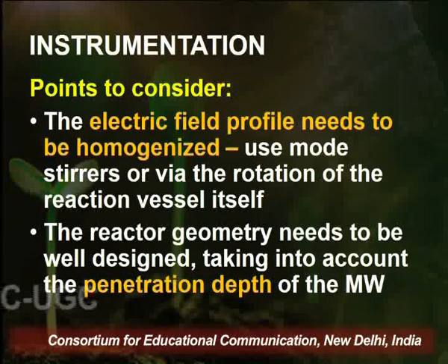We will discuss how this rotation happens further when we discuss the microwave extractors or their components. Then the second point that has to be kept in mind is the penetration depth of microwave. As we discussed, the heating by microwaves is also dependent upon the penetration depth of the microwaves into the object. So we have to design the reactor in such a manner that the penetration depth of the microwave is not affected. No matter how large or how big a microwave extractor or reactor we design, penetration depth should always be considered before designing the size of the reactor.